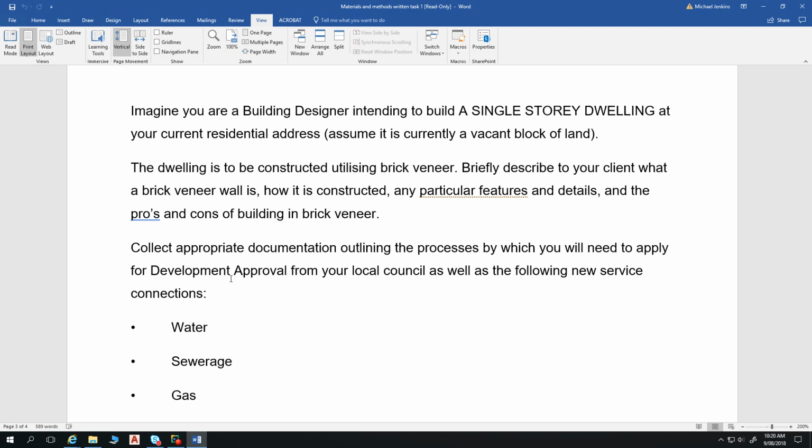So for their studs, that's our piece of timber like that. But if we were to cut through one of the steel studs, it would be something like that, and then have some little bits here like this through our stud. So some form, and it would be of a certain thickness, let's say 0.6 or 0.8 mil thick. The manufacturers of those studs, they own that design. They own essentially the intellectual property around the capacity for how those studs work, how they're integrated, all the joining pieces, etc. They can do all the design using their own design software.